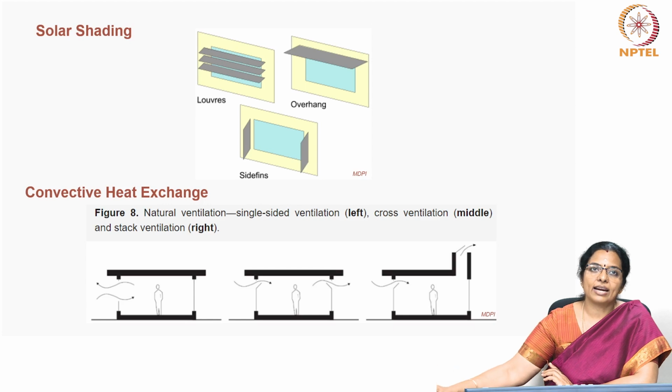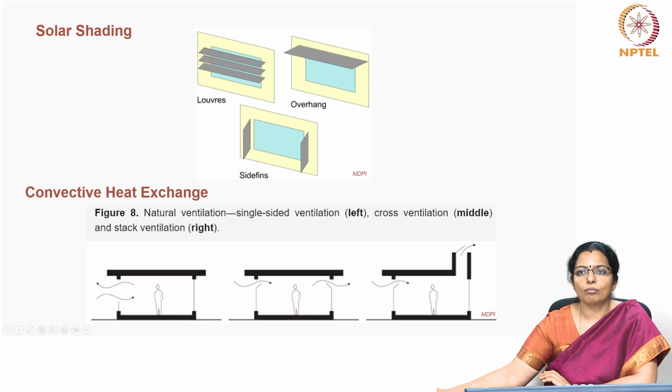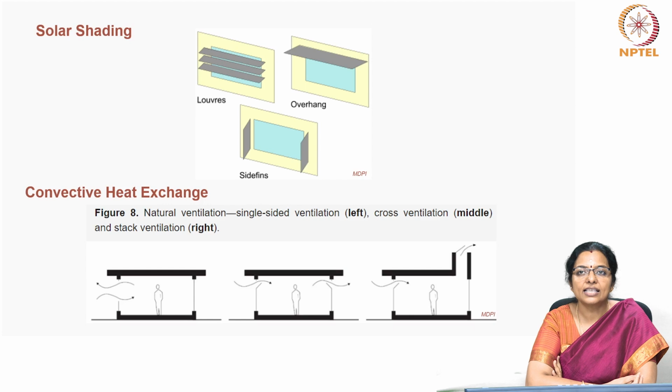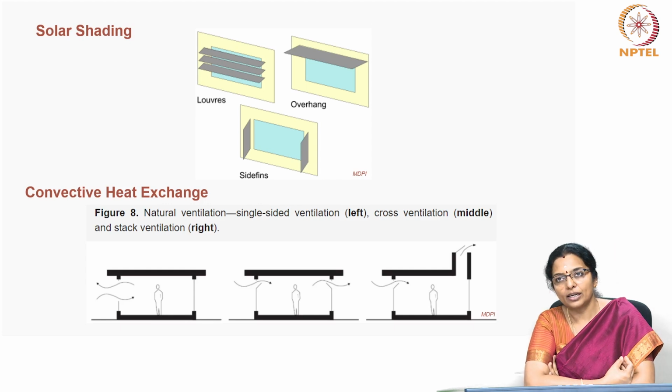When the indoor environment is too warm and the comfort is compromised, the air movement around the occupants may be increased. This can be done using natural ventilation techniques, often categorized as single-sided, cross-ventilated, or stack ventilation, and also through wind catchers or wind towers.